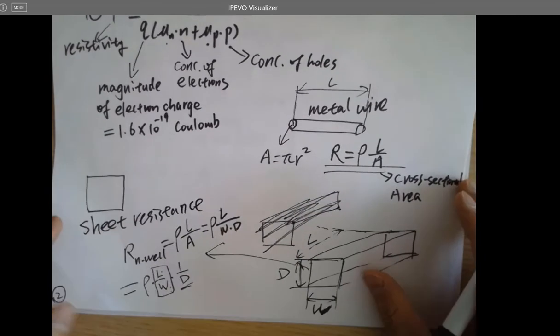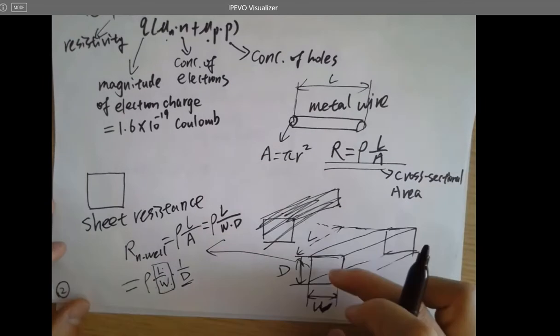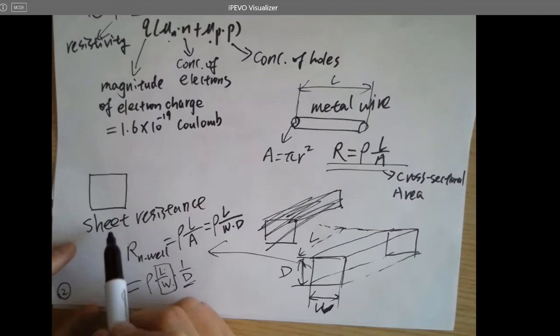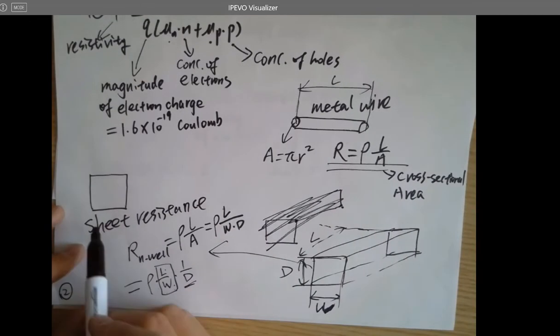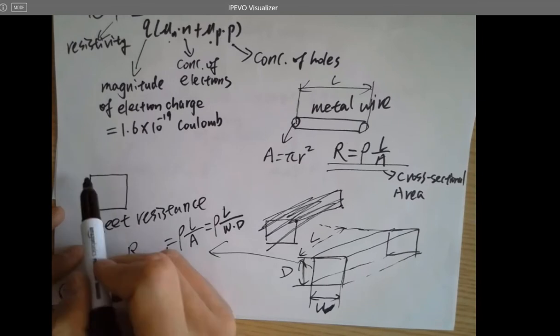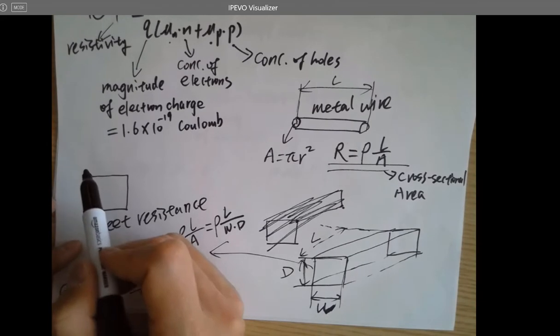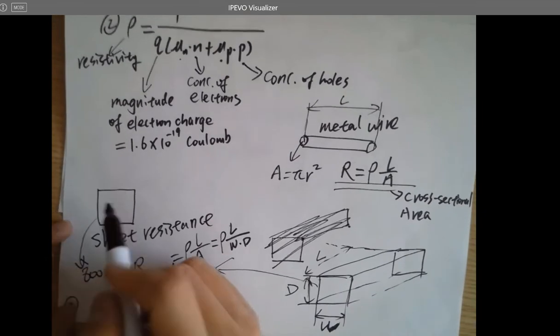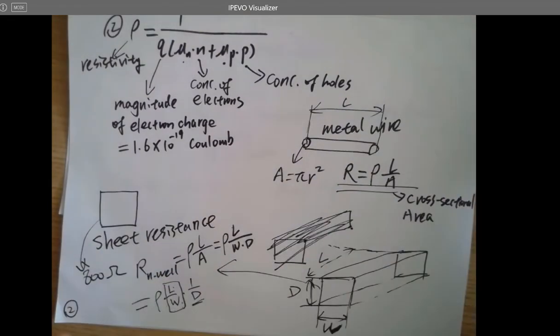It can be applied to both the N well and also some other resistive materials we are going to use in the future in this class. The polysilicon, the same material as a gate, can be used as a resistor as well. But this is the N well resistor, and this is the concept of sheet resistance, which means that every single square is 800 ohms. Doesn't matter how big the square is, right? But you have to follow the rules for the C5 technology.